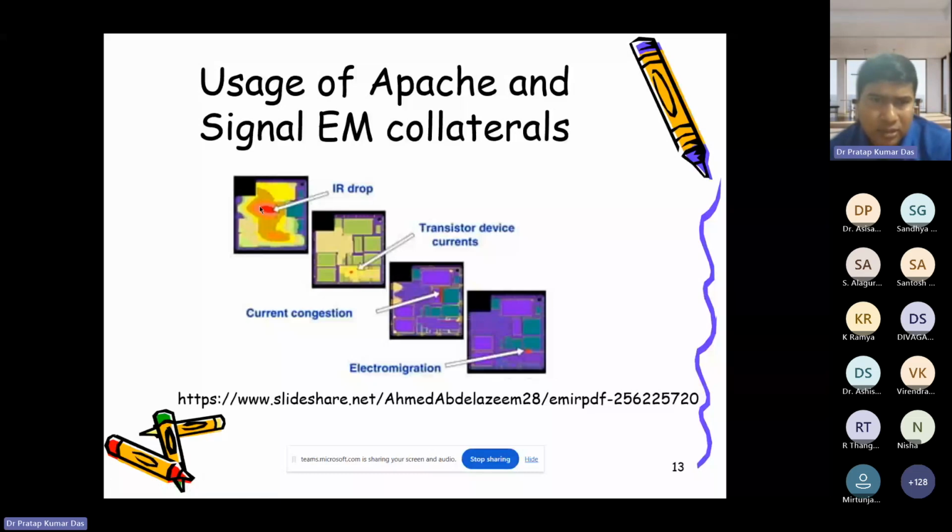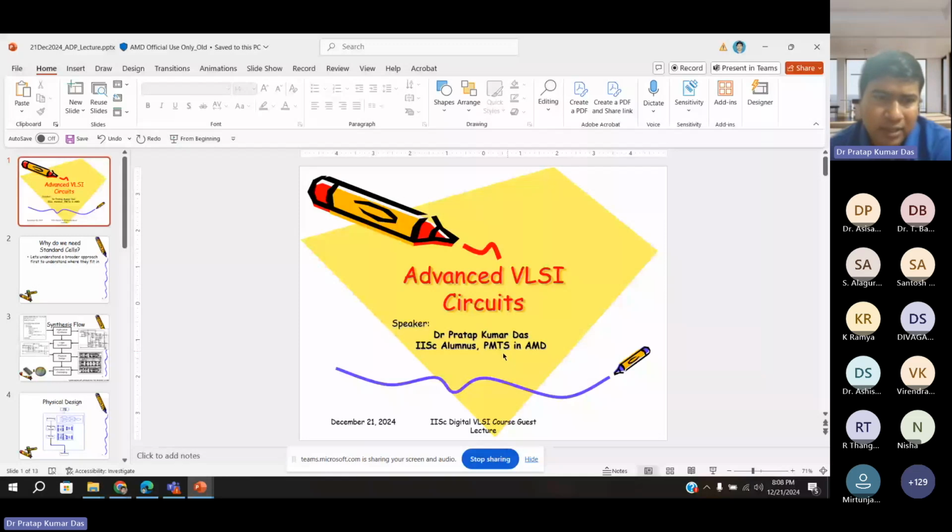So as you can see, this is the first level, and then after some time it goes through. Here you can see after multiple uses, for the electromigration, the metal gets melted. So this is the intent of the IR drop analysis. What we do is simulate and give a heads up. Then you change the circuit, improve the standard cell used here, and make sure that in the simulation you don't go to this bad state. So this is part of the standard cells. Okay, I would like to then touch upon one more thing, that is fault memory.